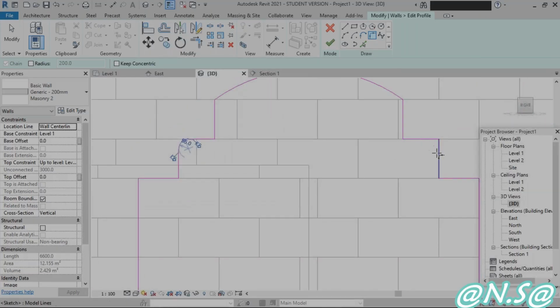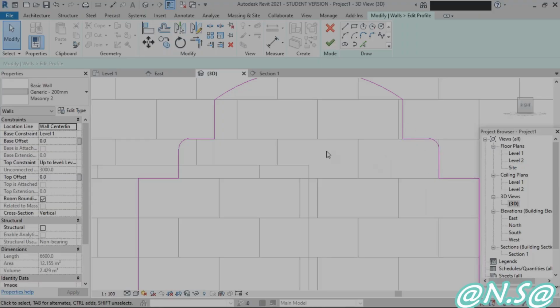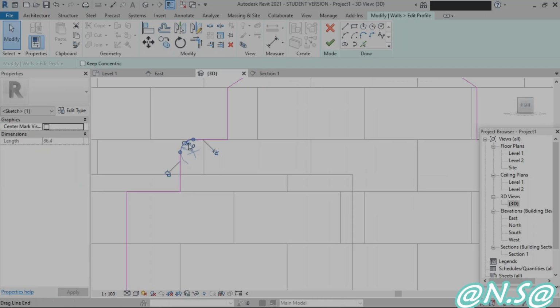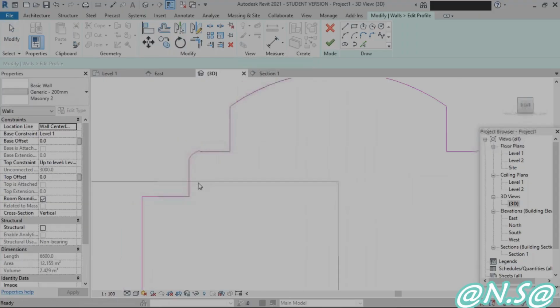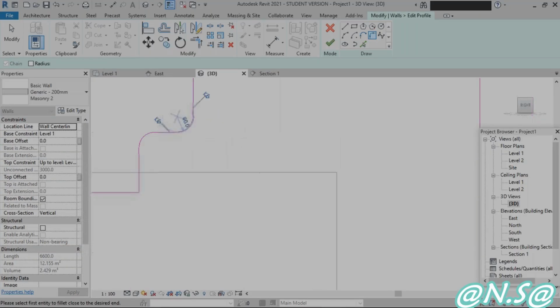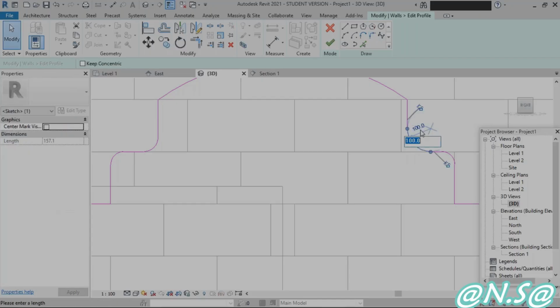The same thing I can do here. Now it is 160 here. Let us change this by selecting this arc. Select 55, enter the value 55 and then press enter. We'll get the same thing. Cross check, yes, this is 55. Even these corners also we can go for fillet. Two lines you need to specify where you like to create the fillet. Here the radius is 60. Let us change it to 60. After drawing we can change it by selecting it.